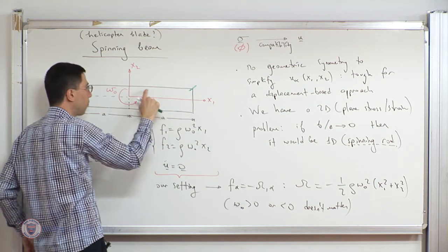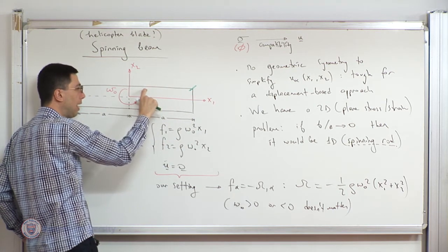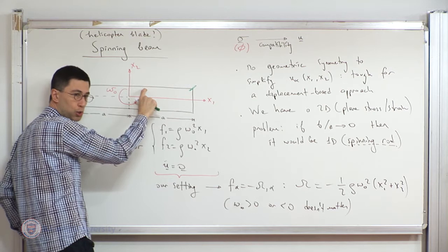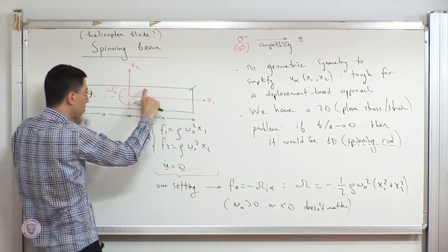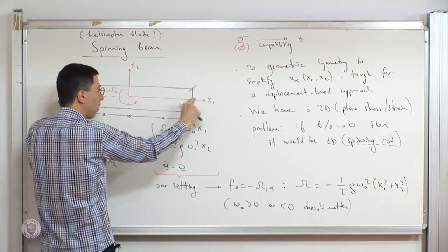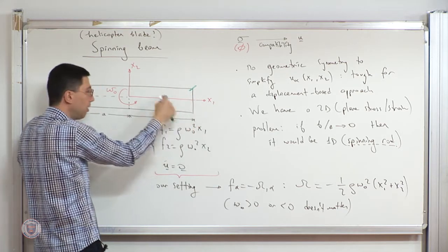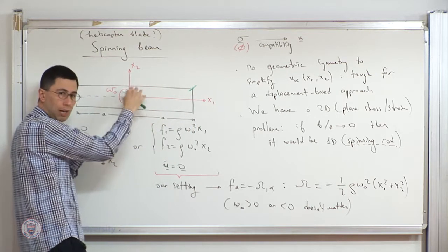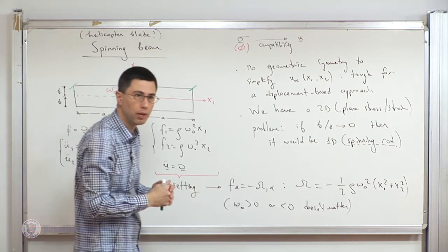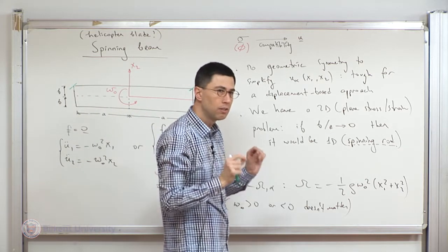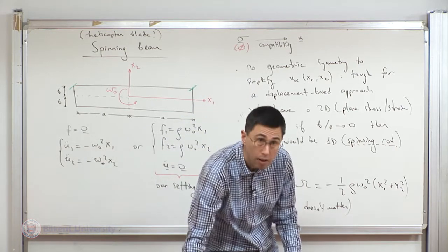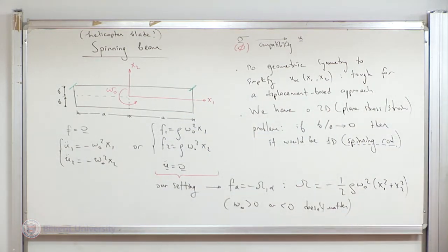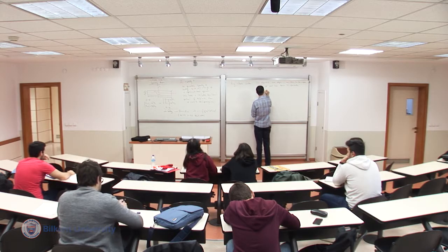And in particular, sigma 1,1 here and sigma 1,1 there should be the same. Does that make sense? Because this thing is trying to expand, the profile here will be the same as the profile there. So the stress will be symmetric. Likewise for sigma 2,2. So I know that the stresses will have a certain symmetry with respect to the coordinates. I'm going to call that stress symmetry.